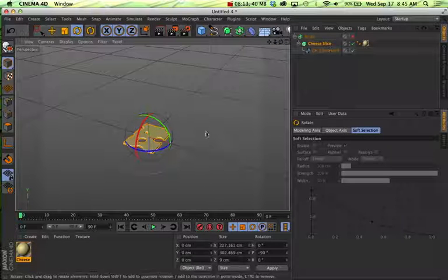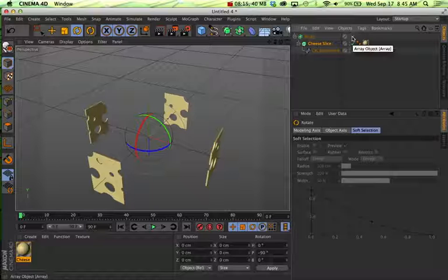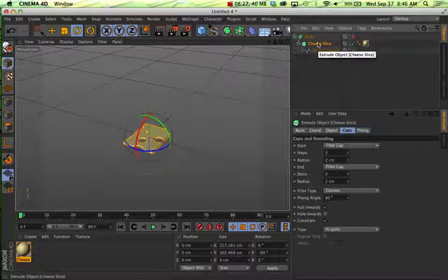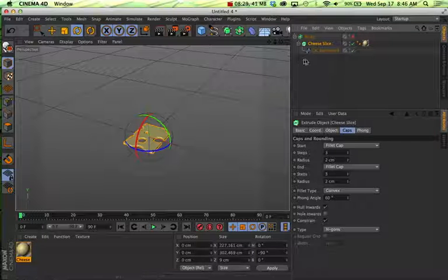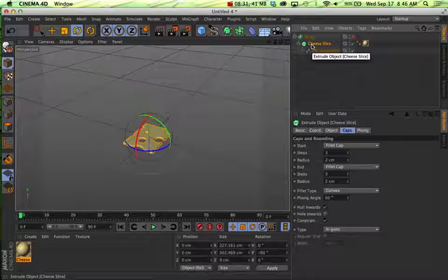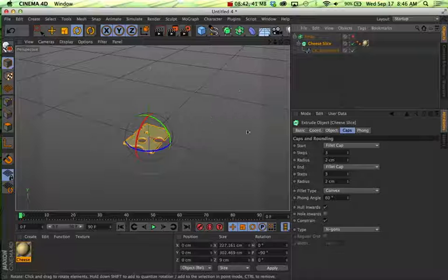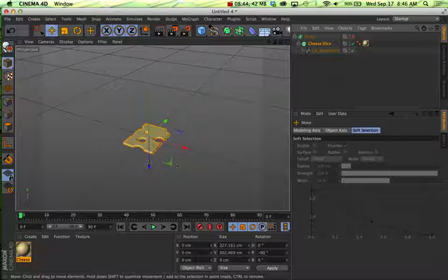So now you'll think, okay, well, it's rotated, it should work. Well, it's still not going to, because it's using the axis of the object, and the array automatically lines it up with the world axis. So we actually have to get in there and change the axis of our extrusion. If we wanted to keep it editable, we always need the extrusion to be lined up in the world axis. So if I hit here, we can see it's back.